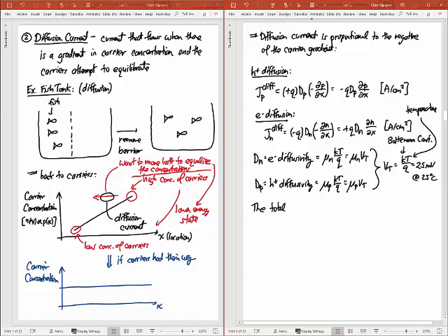Okay, and so just to finish this all up, the total current at location x, which is kind of an interesting thing. The current can change with the location based on what the slope is at that location. I could say J total is going to be equal to J total of the drift plus J total of the diffusion, where J total of the diffusion is just these two added together, right?